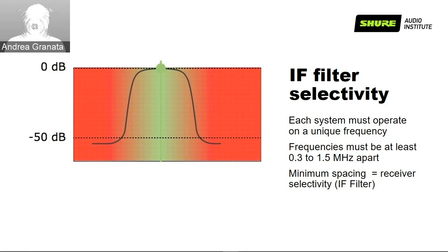But the wider the filter can be tuned, the less selective it is. So if we have a wide tuning range, our filter will not be as selective as a narrow band filter. If my device is capable of tuning in a range of 20 megahertz, I can have a pretty selective track tuning filter.